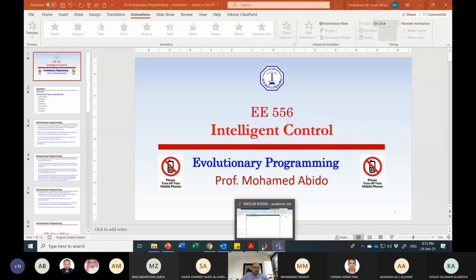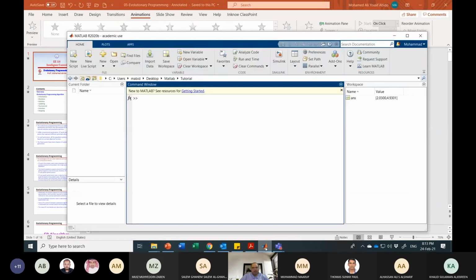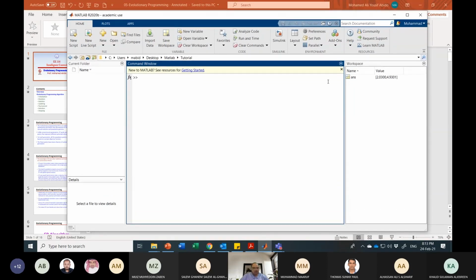As per your request, some of you requested just a brief tutorial. Definitely you can enjoy it, and you can go and train yourself. So what we will do here is a very simple example and how to use MATLAB to solve a genetic algorithm problem.